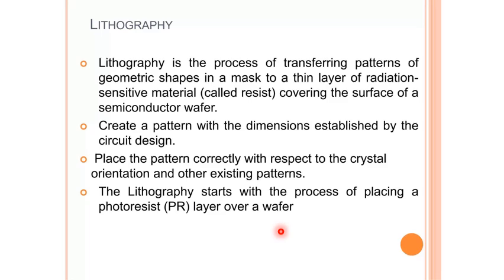Okay, so photolithography consists of a photomask, or simply a mask, and some photoresist must be covering the wafer. So after the initial patterning of the photoresist, barrier layers such as polycrystalline silicon, silicon oxide or silicon nitride can be used as the physical mask on the chip. This distinction will become more apparent as the discussion progresses.